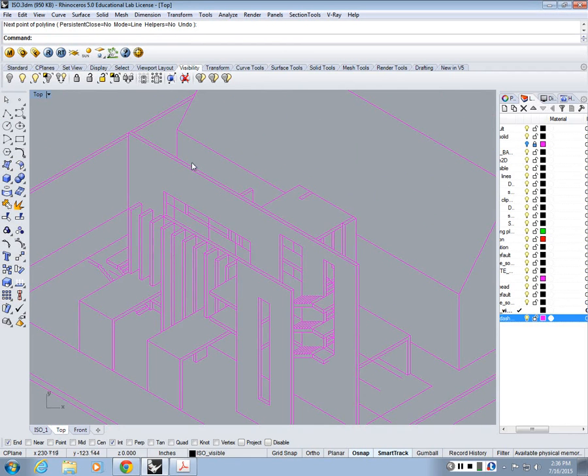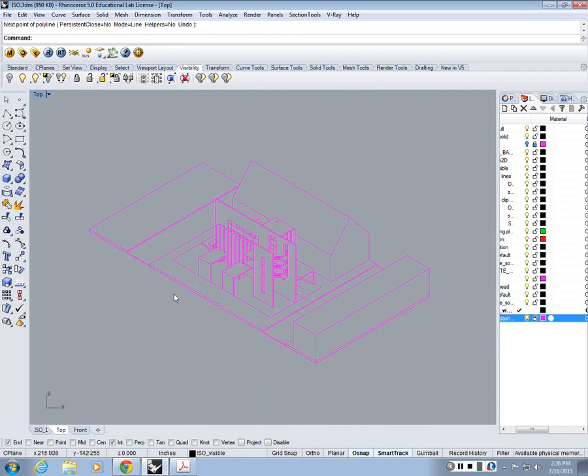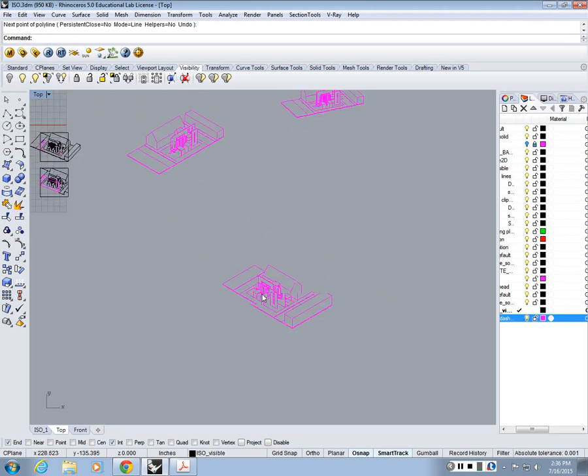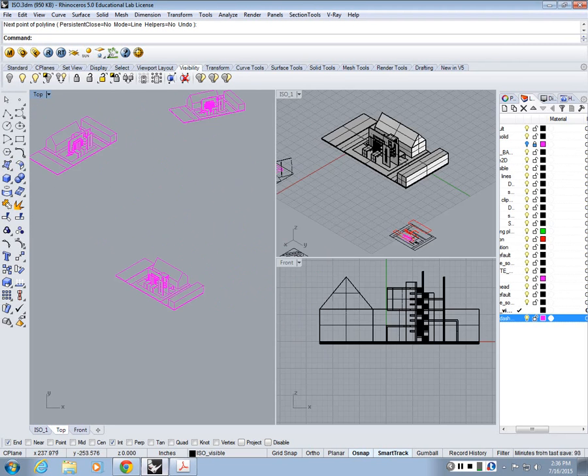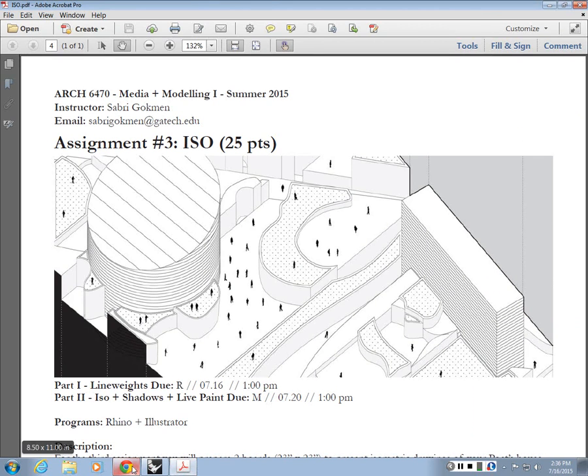The reason I'm saying that is because if I draft it in this scale, then I can do the 1/8 inch equals 1 foot conversion. And my isometric will be up to scale, right? So you could technically draft it 23 by 23 and place your drawing inside and make it into a precise drawing basically. You can even write scale under it if you wanted. Okay? I actually did this one that way, I think.